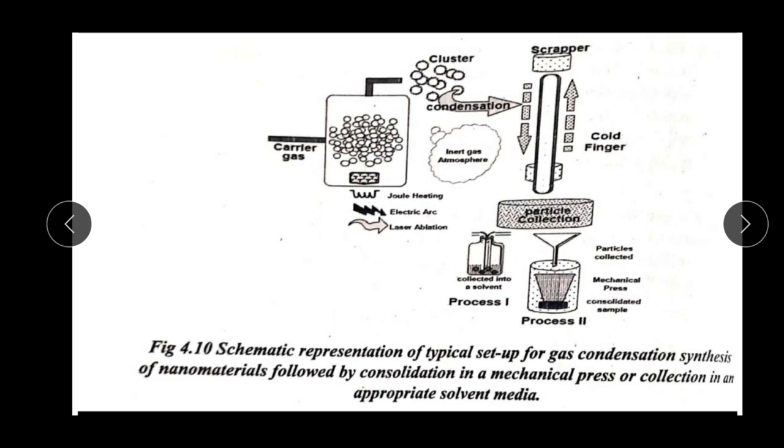Dear students, as you can see in the image, the cluster or particle size depends critically on the residence time of the particles in the growth system, and can be influenced by the gas pressure, the kind of inert gas, that is helium or argon, or helium and argon, and on the evaporation vapor pressure of the evaporating materials. With increasing gas pressure, vapor pressure and mass of the inert gas used, the average particle size of the nanoparticles increases.